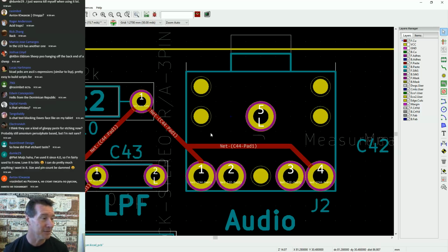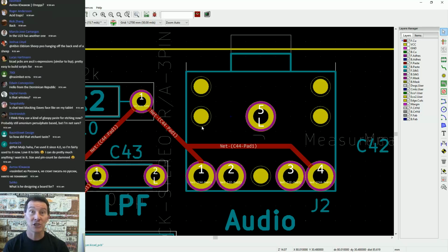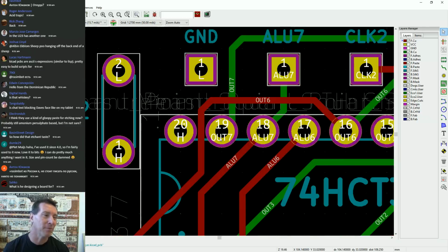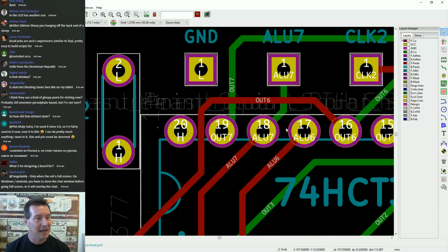And PCB packages will have options. They'll auto chamfer your traces for you. Some people like that look, and I don't blame them. It's pretty funky. I probably went through a fillet phase. And the other thing is teardrops as well.